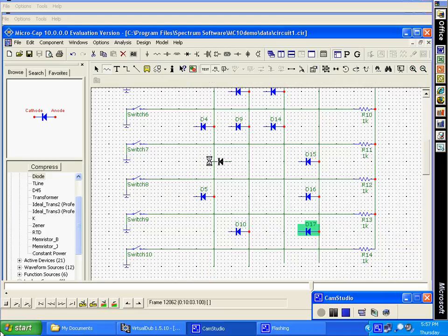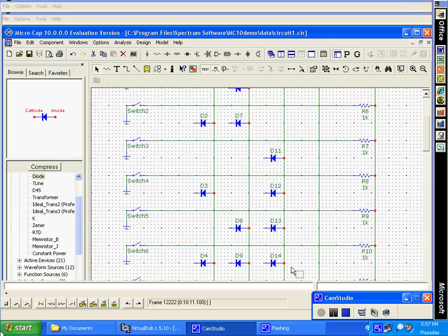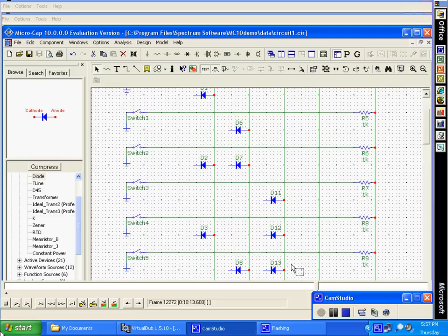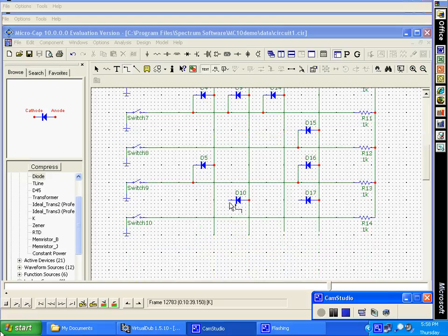the wiring icon, and we start adding the wires that hook these to the switch lines. Click, hold, and unclick for that point. So we're down to the last two wires that we have to add. That is added. I hit the escape key. We now have our completed circuit. So we're now ready for testing.